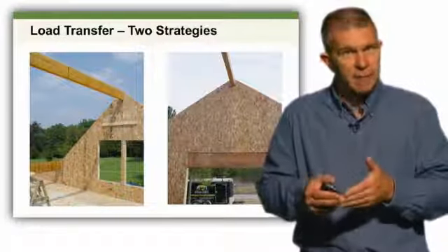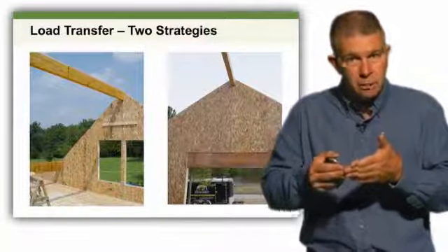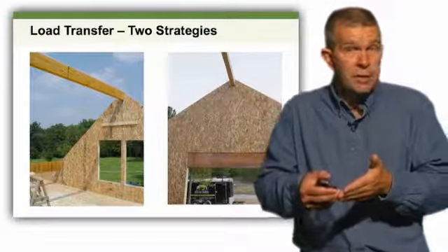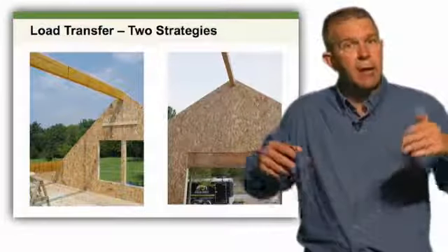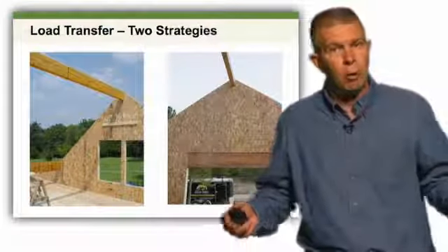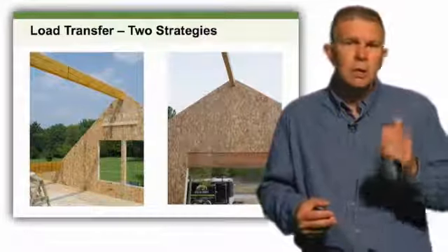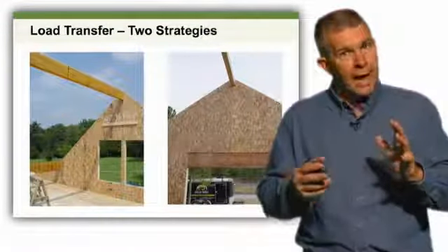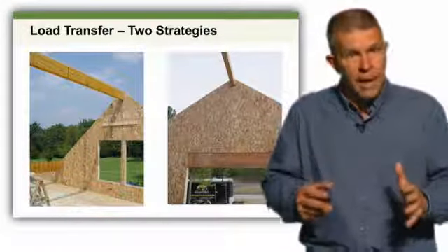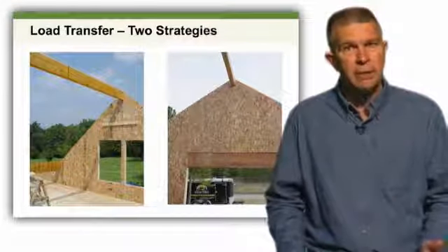And once we hit that conventional header, that point load has been determined that one, a header is needed, and the posting, when transferring the load to the header, now carries that load around the window opening into jack posts and on down. So point loads are something that you have to be mindful of as to how you're going to get that load down through your wall system and around and into the foundation.